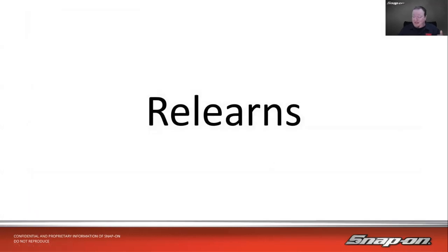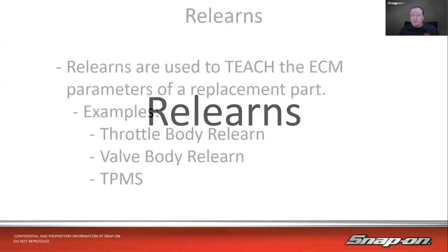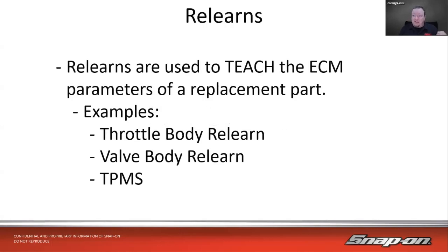So resets, like I said, fairly straightforward. Usually it's going to be clicking a button on the screen and really not a lot of other things that need to be done along with it. Now, relearns are along the same lines, a similar vein, but oftentimes they're going to take a little bit more time. They might even require an action from you, or it's going to be an action that is actuated inside the vehicle. So relearns are used to teach the ECM parameters of a replacement part.